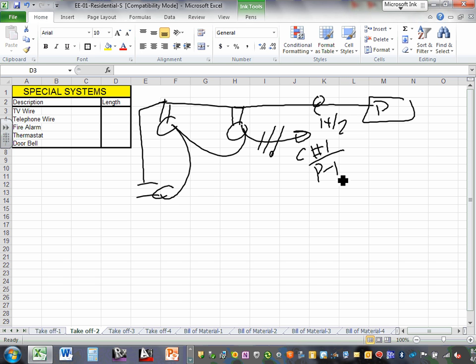So for the sake of the calculation, guys, make sure the height is 10. When you go up, you go 9 feet. When you go down again to a receptacle, you go 9 feet. If you go up to a switch, make sure the switch is 4 feet. When you go up, you go 6 feet. When you go down to a switch, you go 6 feet. The switches are higher at roughly 4 feet. Does that make sense? And move in right angles.